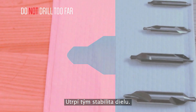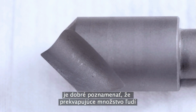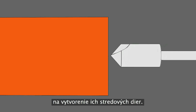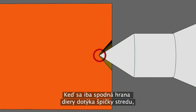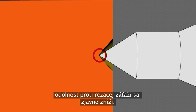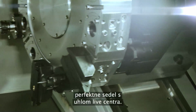Part stability will suffer. And though it may seem like an obvious point, it's worth noting that a surprising number of people will mistakenly use a 90-degree chamfering drill to make their center holes. This is what the contact looks like when a 90-degree chamfering drill is used. With only the bottom edge of the hole touching the center's tip, resistance to cutting loads will obviously be reduced. Always use a 60-degree center drill so the angle of the drilled hole will perfectly match the angle of the live center.